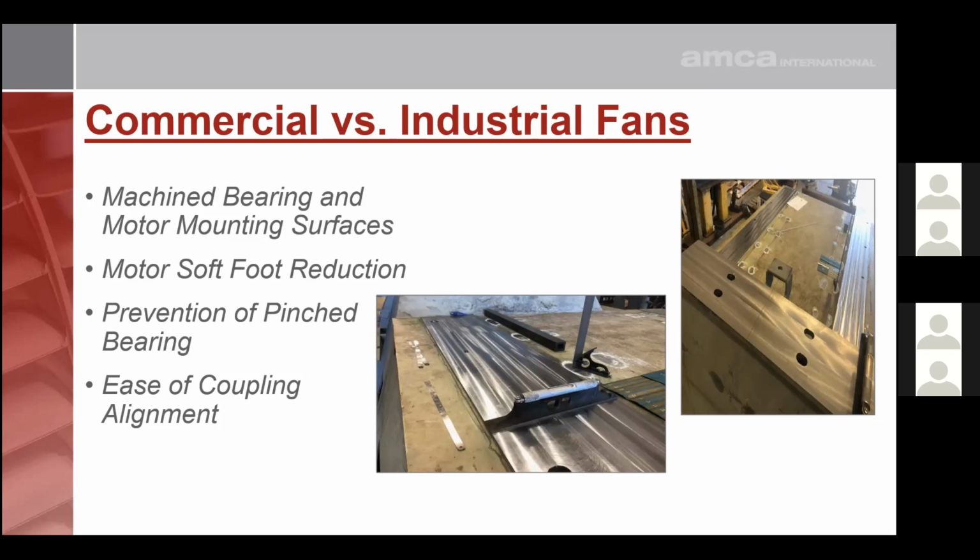Machined surfaces also improve the ease of coupling alignment in direct drive applications. If the motor and fan bearing mounting surfaces are not parallel, the fan and motor shafts will have a vertical angular misalignment. This misalignment can be difficult to correct and requires the use of taper shims or step shims. And similar to having a point or line contact, those step shims have the possibility of loosening over time, and they can result in increased vibration.